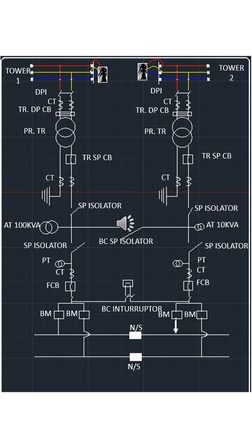When the traction transformer is charged, you close the single pole isolator of the transformer after the CT. Then it is the no load switch. First you have to close it. Okay. Next, what you have to do? You have to close the single pole circuit breaker. Then the power will be fed to the common bus. That means coupling the two buses.